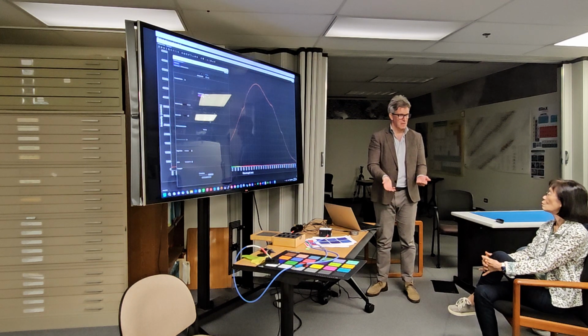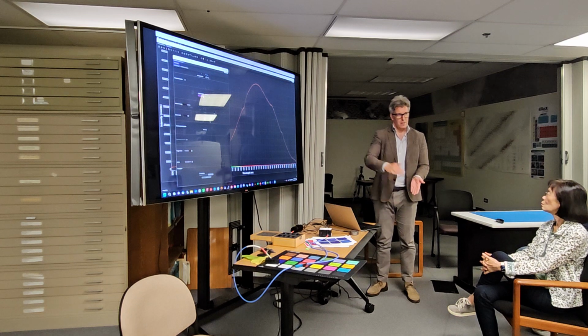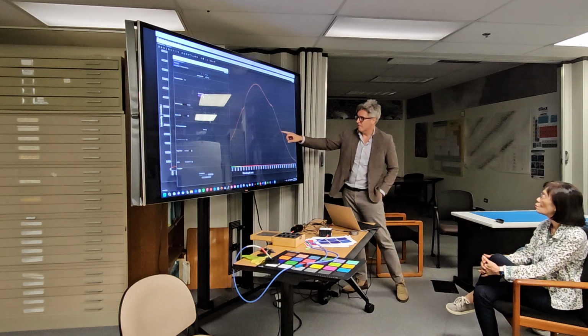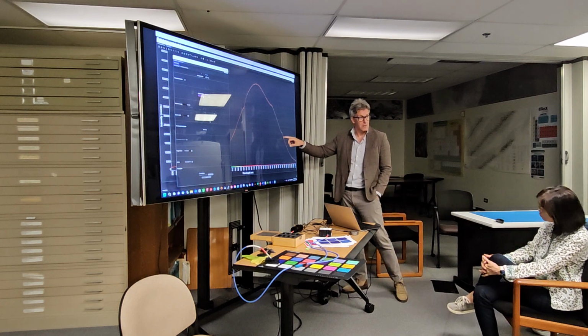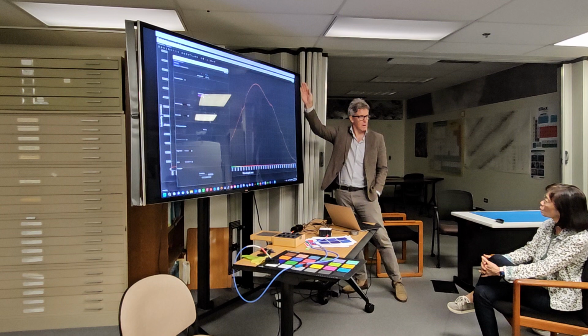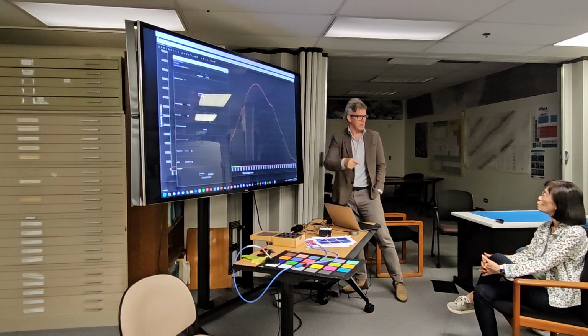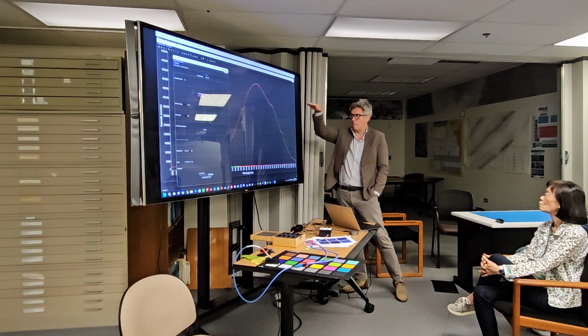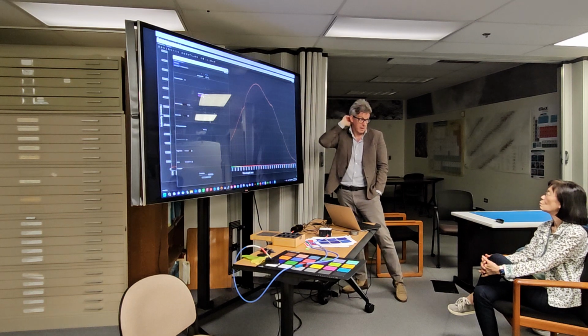And there's no information there. The larger the dynamic range, the more bits I encode, the easier I can identify very subtle peaks and troughs in this curve. So I want to maximize that signal, but I don't want to saturate, because if I saturate, I have nothing. I have these flat plateaus where I really don't know how much light is reflected.